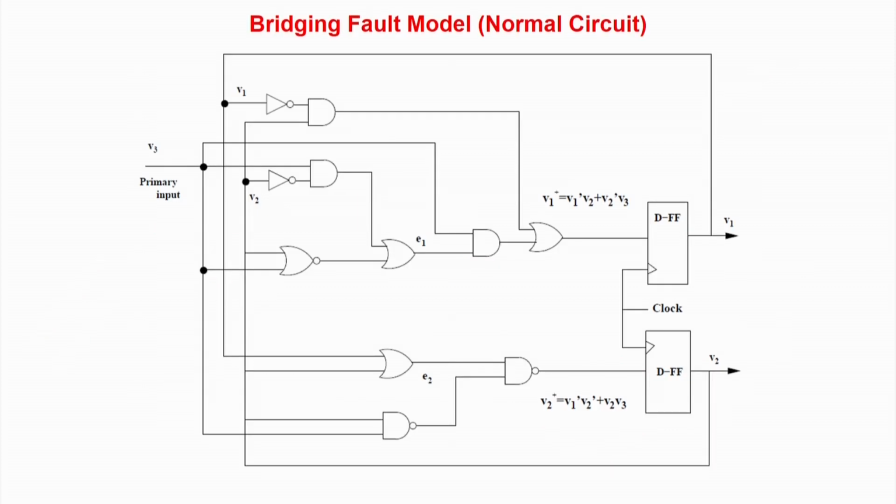So let us take a very simple circuit example which we will be using throughout. Now I will mainly be talking about sequential circuits as examples, because we already know the scan chain. Scan chain means you can directly set or reset your flops. So these are simple circuits, with 2 lines. Any 2 lines may have a Stuckat fault, thus any 2 lines may have a bridging fault. So now one thing is there.